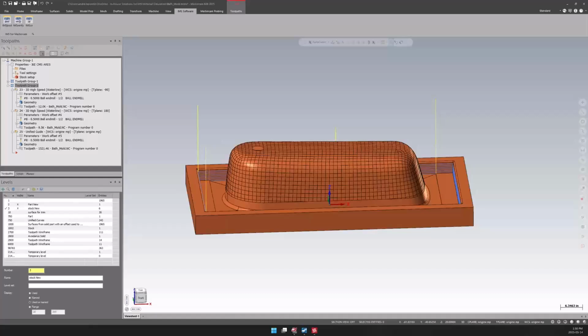And if you're using variables to control the behavior of some of those macros or motions, just make sure that the initial values are set somewhere in the program when you start the simulation, because obviously the simulator will not know offhand what values are set on the machine by the operator, for example, and then it will simulate and work properly.